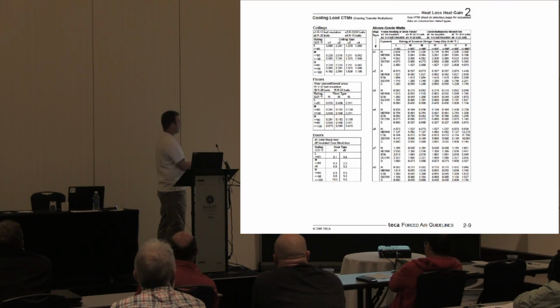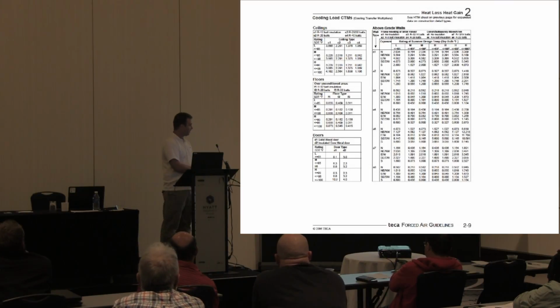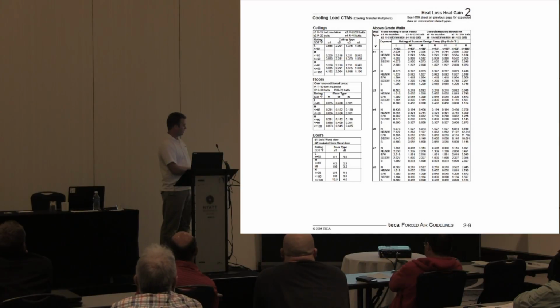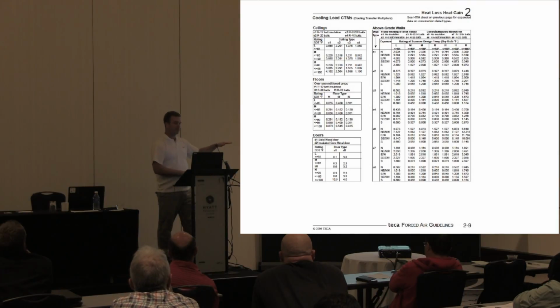But basically, if we count on you living in a certain district, we'll just say that it's, whatever, 80,000 BTUs. The way this chart works is you draw a line down from 0, we lose 0 BTUs down here, and we draw at 60, and we draw a line across, and then we draw a line for the capacity of the heat pump across, and where they cross is where the heat pump is.